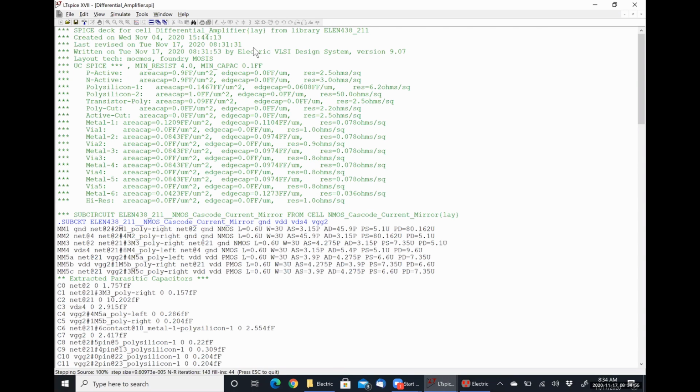So an NMOS transistor with a resistor connected at the source, and use that as effectively just a unity gain buffer to pull our output voltage down from oscillating around 4 volts to oscillating around VDS SAT plus VTH, so somewhere in the region of 1 volt. And then I was going to call it a day so I could get to work on some of that stuff. But this is taking a long time.